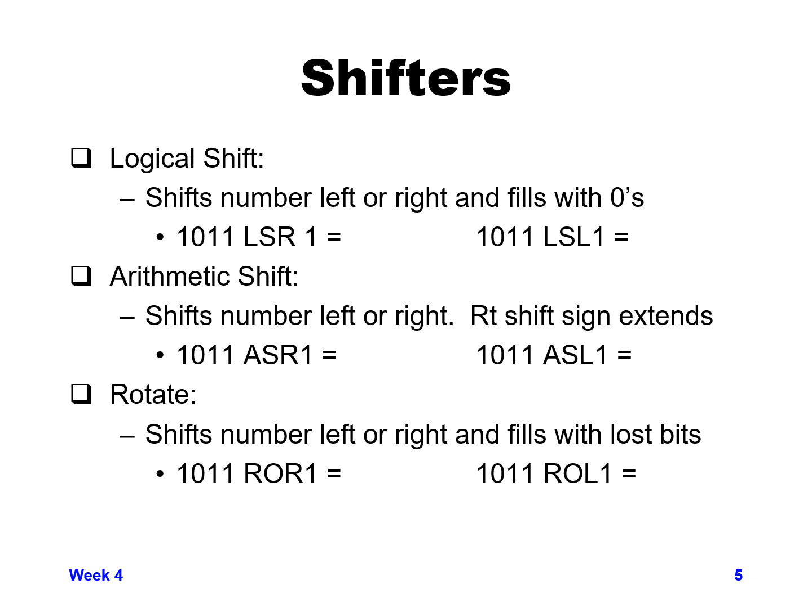So if we do a logical shift right of 1, 0, 1, 1, we fill the leftmost position with a 0, and we shift everything to the right and lose our rightmost bit. So bits 3, 2, and 1 are now bits 2, 1, and 0, a 1, 0, and a 1, and the leftmost bit is a 0, and we've lost the previous bit 0, which was a 1.